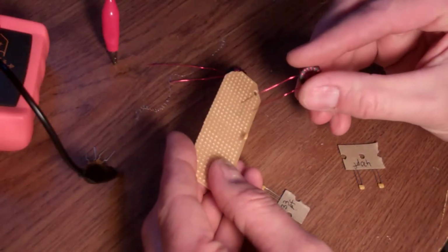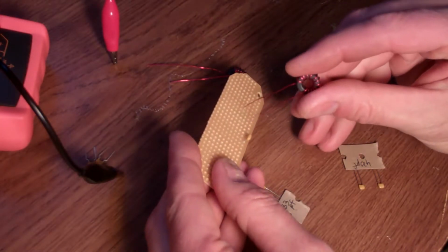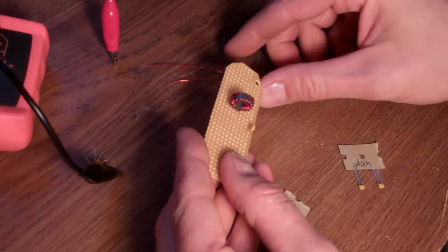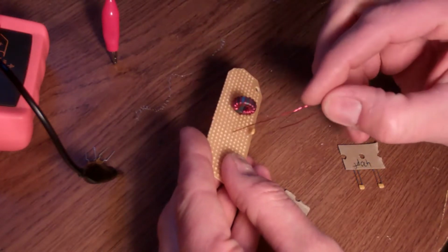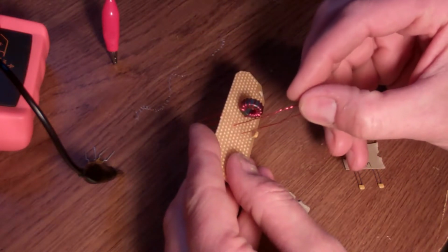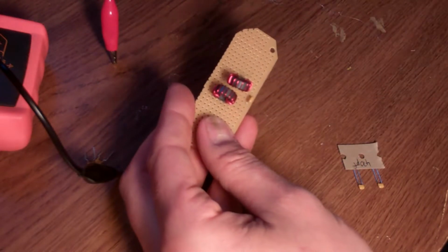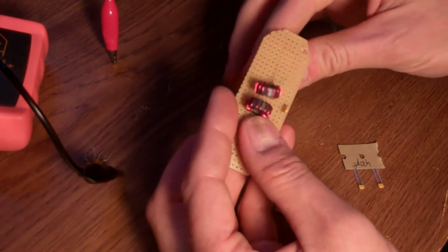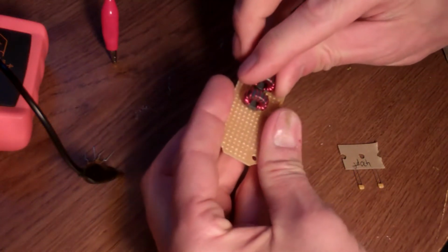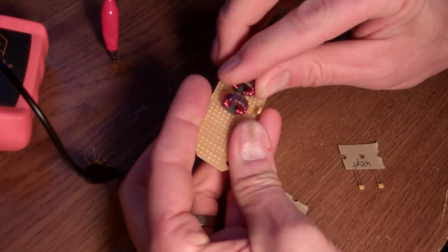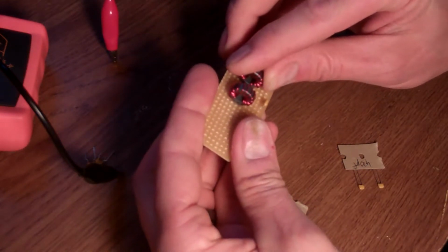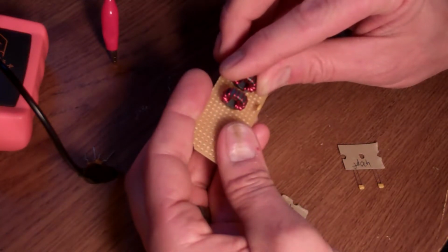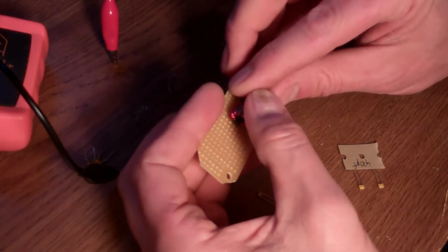So the next thing I like to start doing then, after I have everything all settled and all the components selected, is to start laying out the components on the board before I solder them. And then to kind of put the inductors in place, put a little blob of hot glue on there so I can keep them oriented and separated to whatever I need them to be. So I'll just let that cool for a second. And once I have all the other parts on, then I will be ready to solder.